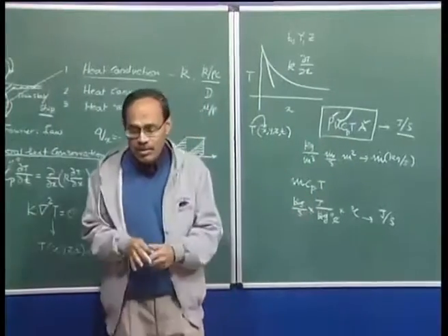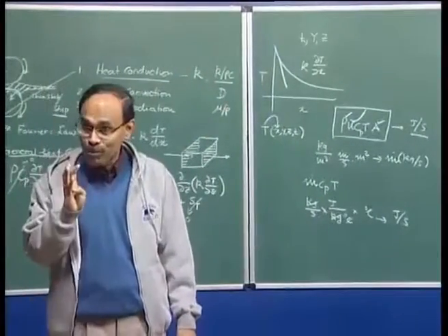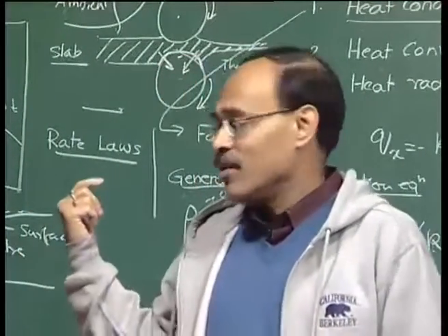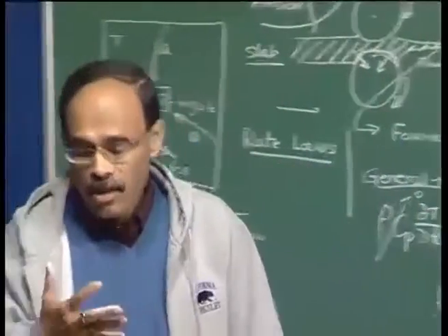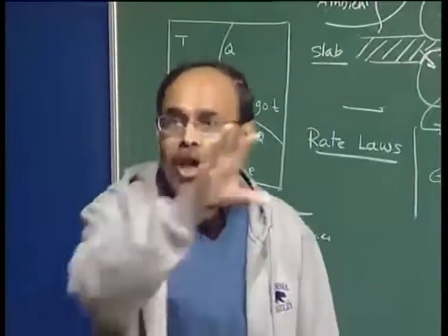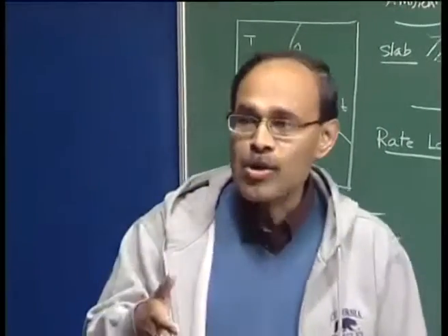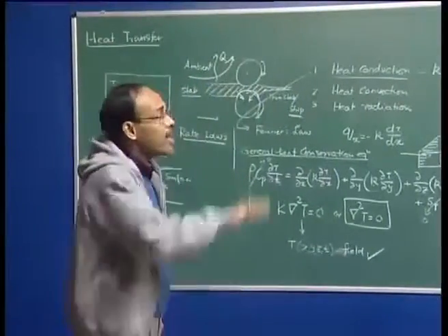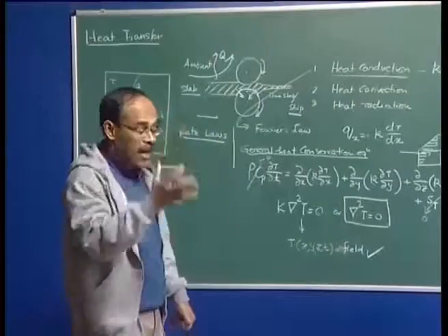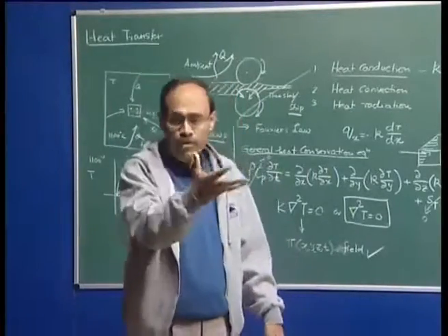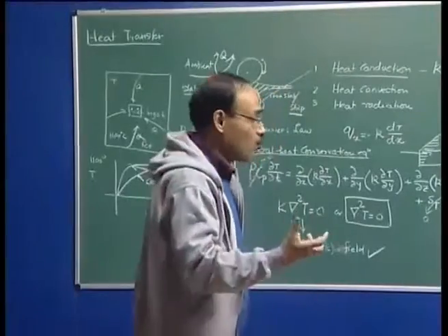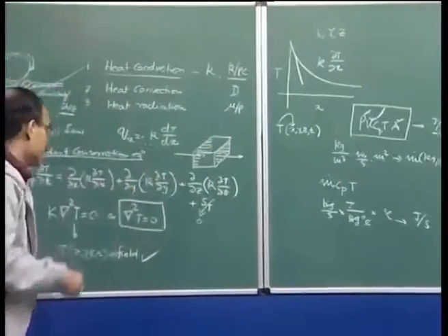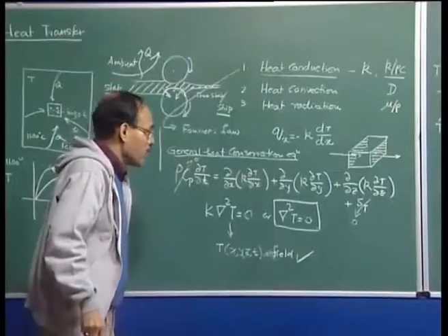And how do you know fluid flow? We know fluid flow either through experimental techniques, where we insert a probe and find out the velocity, or, as I indicated in the previous lecture on fluid flow, we have governing equations which are nothing but the Navier-Stokes equations. Once we solve the Navier-Stokes equations, we have a very good idea about the fluid motion in the system itself. And having obtained information about flow in the system, we should be able to calculate convective heat transport, provided we apply a similar energy conservation equation.